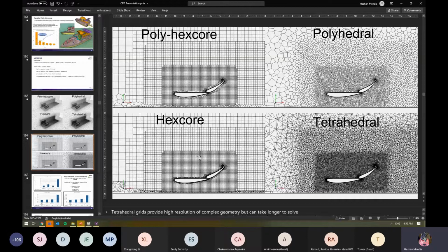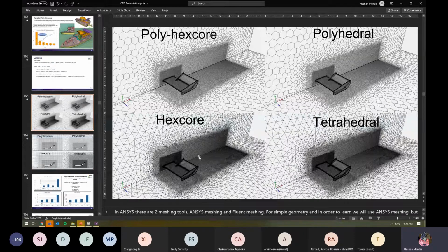How do you decide what your target Y plus is? Again, there's no easy way to determine that. So generally for something like the wing, what you'll start to find is that what you want is a Y plus of 1 to clearly model the viscous sublayer. And sometimes there are some studies that even go down to like 0.2, depending on how accurate you actually need to get. But like we talked about, we're always thinking about trade-offs.